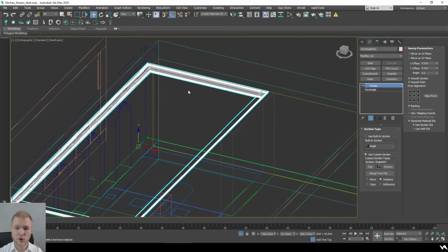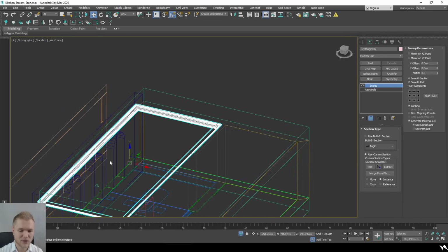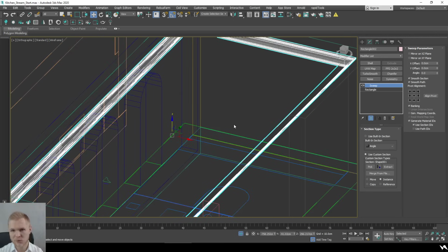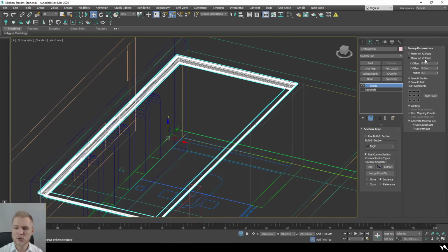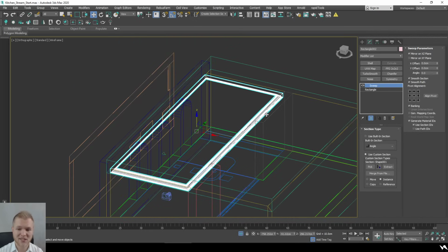So luckily there's no problem with it other than just, well, it's mirrored. If you have this problem, you don't have to necessarily go inside your object and try to rotate it this way. You can just try to mirror it using the proper plane. So you can either try to use it in XY or XZ plane, and XZ actually worked the best.